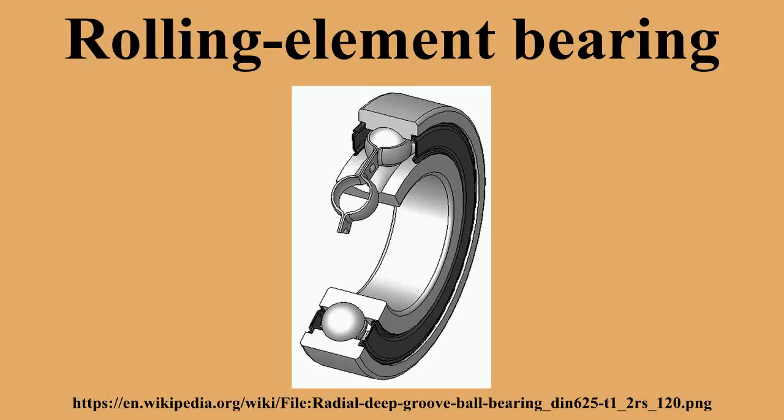Design. There are 5 types of rolling elements that are used in rolling element bearings: balls, cylindrical rollers, spherical rollers, tapered rollers, and needle rollers. Most rolling element bearings feature cages. The cages reduce friction, wear, and bind by preventing the elements from rubbing against each other. Caged roller bearings were invented by John Harrison in the mid-18th century as part of his work on chronometers.